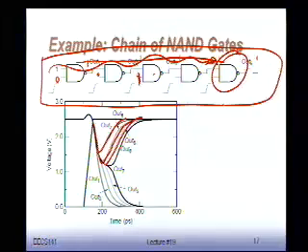What we did is look at the arrival times of the different phases in the carry chain, and saw, hey, this multiplexer has one input which is already sitting there and is ready, and has to wait for the other one to arrive. So what we did is make every block gradually larger, so that we balance the propagation delay to each one of those multiplexers. So that was an example of a topological change which helped us to eliminate not only glitches but also improve performance.